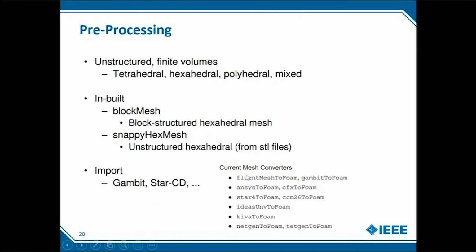In such a case, OpenFOAM has these commands known as fluentMeshToFoam or gambitToFoam, which convert these meshes into OpenFOAM meshes. When you type these commands, it's just writing a mesh file. It's just translating the mesh file. That's it. They had to develop these commands so that if the user wants to have a choice of meshing it somewhere else and just solving it in OpenFOAM, it should be possible. That is what these commands end up doing.